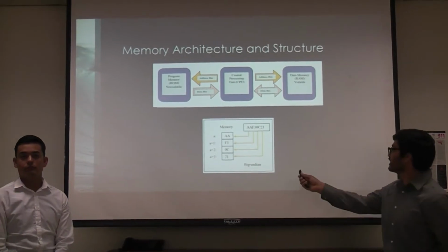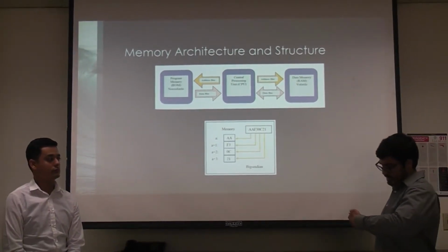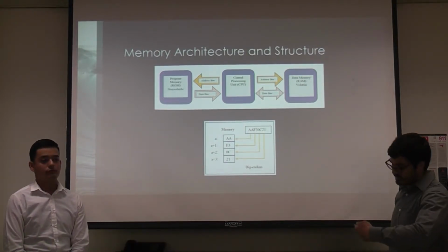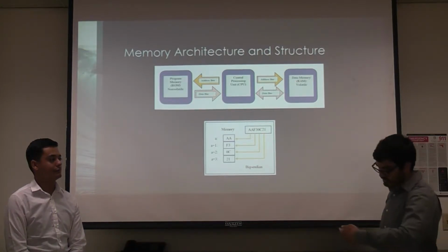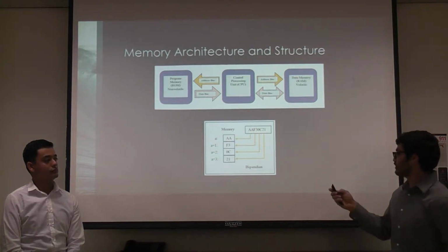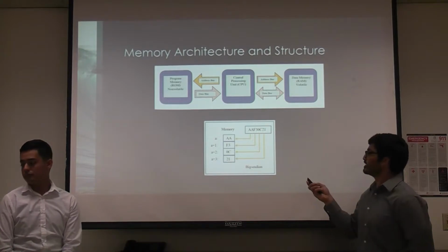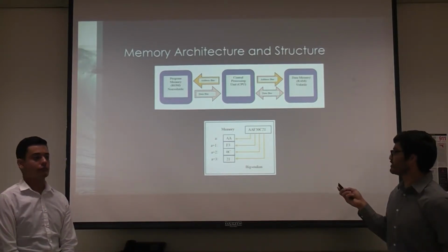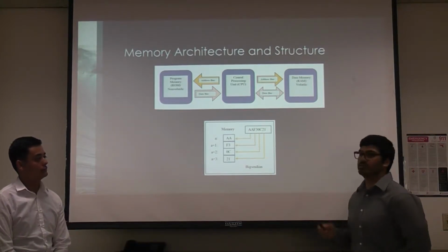Here we have a 32-bit address space with a minimum of 1024 words at 0 hex to 3FF hex. The format that we are using is big endian, where the most significant bytes, 8 bits, are stored in the low address, and the least significant bits are stored in the high address.